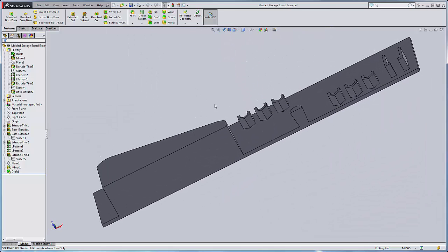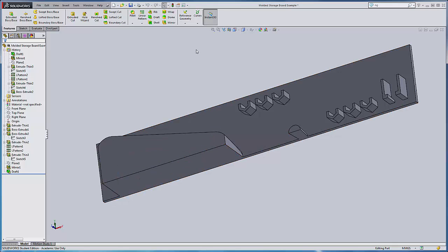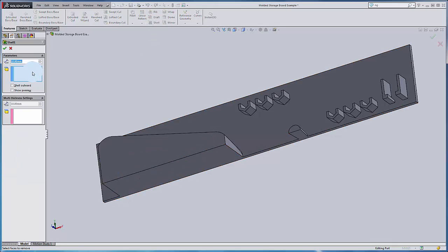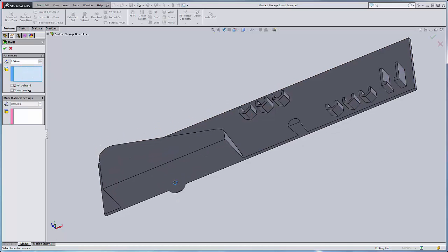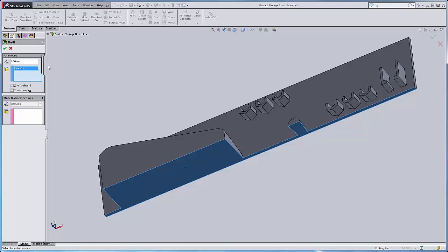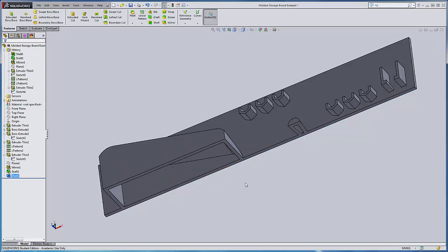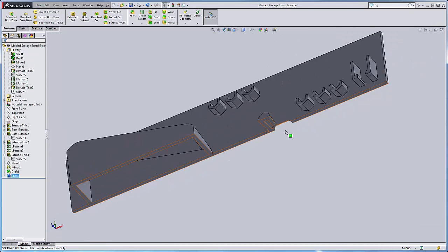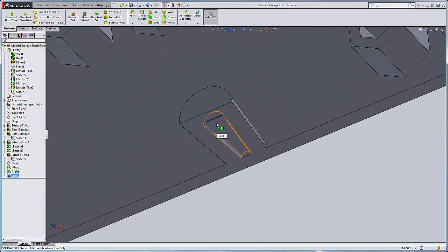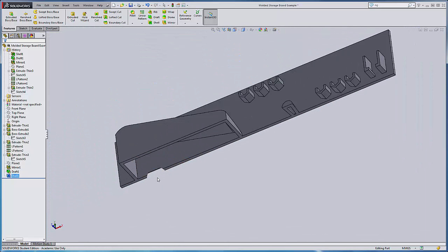And our last major feature will be the shell. It's fairly simple. Click on shell, and you might not want a 10 millimeter thick shell. So we're going to put in 3, and we only need one surface shelled. Sometimes it can get a little crazy and difficult, but here, it's not showing the preview, so maybe it won't work, but it did anyway. So it made sure that this entire surface on the inside here is 3 millimeters from any other external surface, and then it did the same thing here.